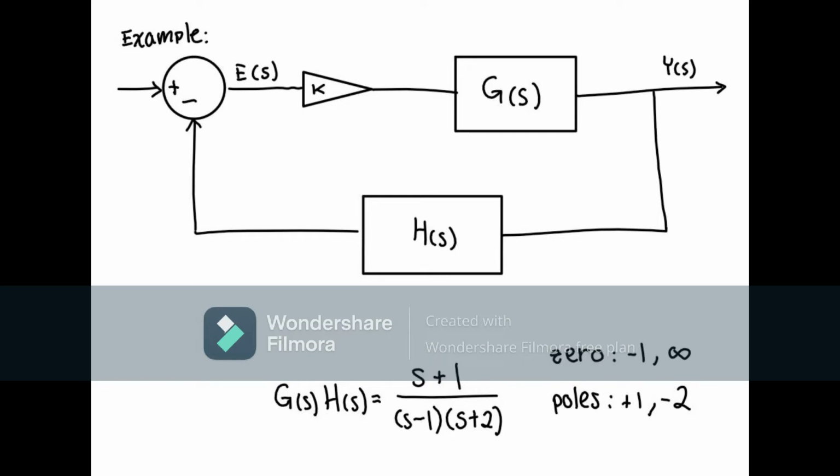It is common to encounter variable parameters such as k in many control system problems. Because this variable parameter is unknown and its value affects the poles of the system, a recurring question is what value of k should be chosen to meet the system requirements, and what is the effect of a variation of k on my control system. Choosing different values for k changes the positions of the poles in the plane, and this is exactly what the root locus method does. It is a graph of the variations of k in the S-plane.